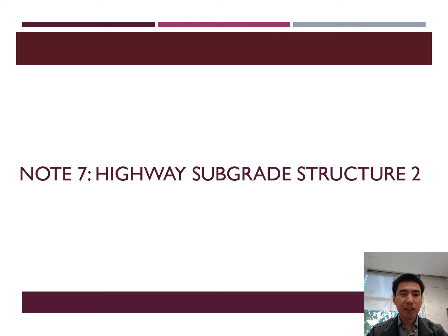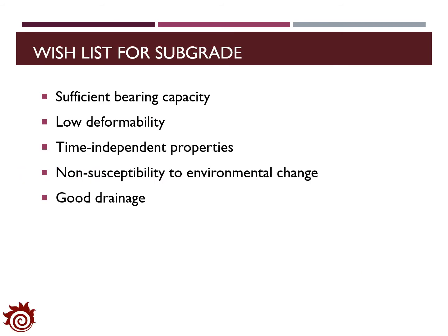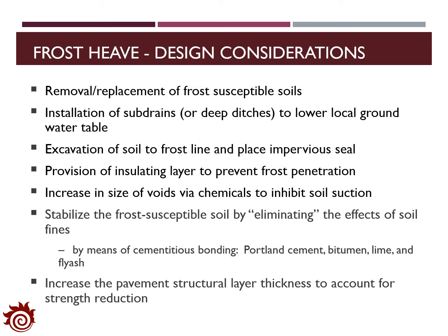Hello everyone, in the lecture today we will continue the topic in the design of the highway subgrade structures. Here is the wish list for the subgrade design that we reviewed in the last lecture. We want the subgrade to have sufficient bearing capacity, low deformability, time-independent properties, no susceptibility to environmental change, and good drainage.